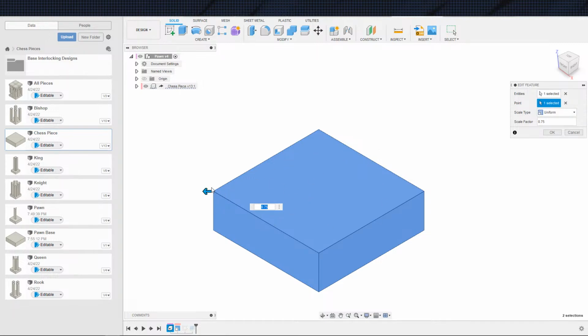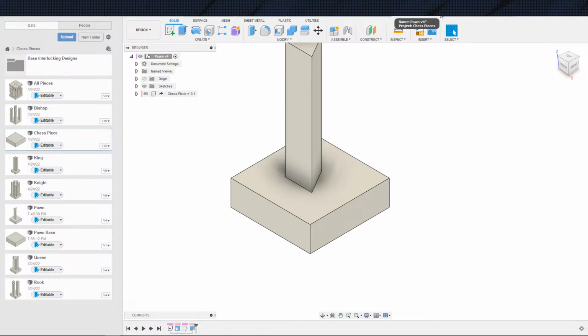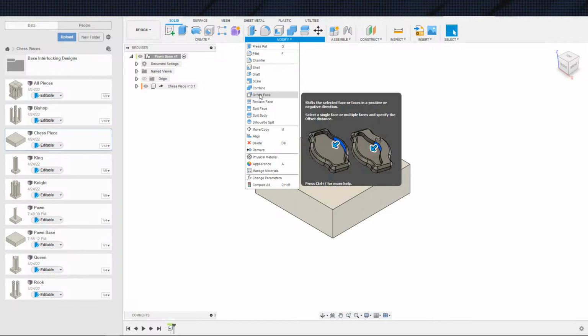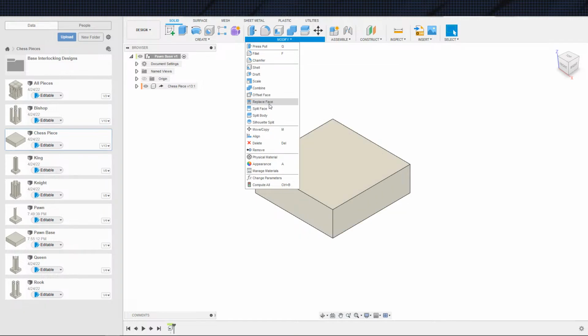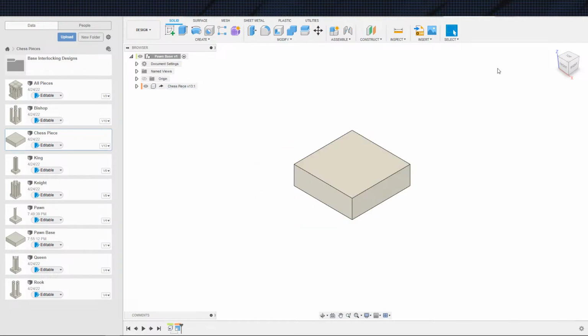I wasn't sure last stream, because I don't use the scale function all too much, what exactly what feature or aspect of the shape I should pick. Evidently, it just picked a corner. So let us modify scale, and I can never find scale because I hardly ever use it. Scale, there it is. That, and 0.75, okay. And this is now pawn base.